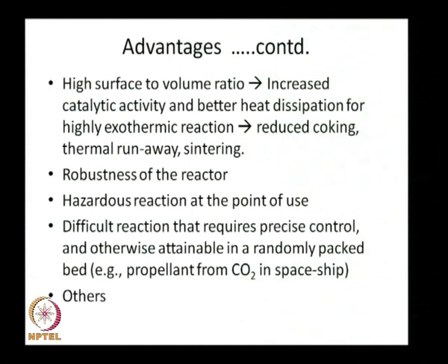Then, difficult reactions that require precise control, and these reactions are otherwise not attainable in a randomly packed bed, such as making propellant from carbon dioxide in a spaceship. So, this is some kind of reaction where you need very precise control. That kind of control is possible in a microstructured catalyst rather than in a randomly packed bed.